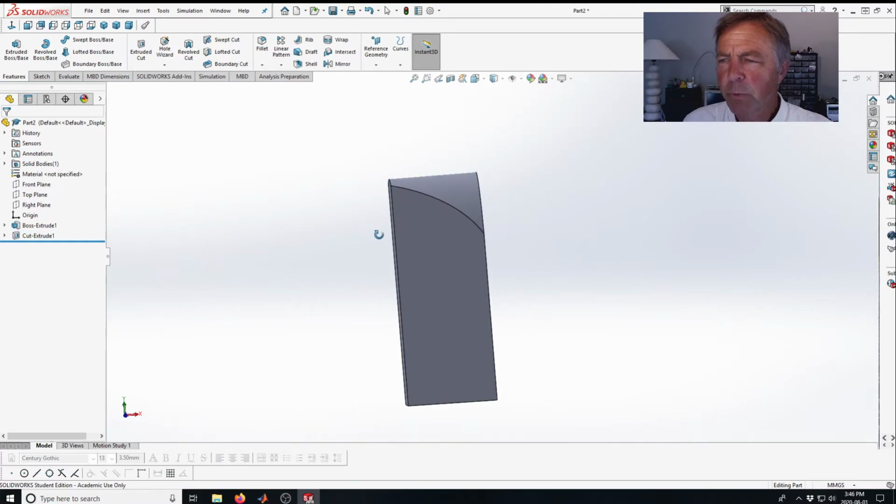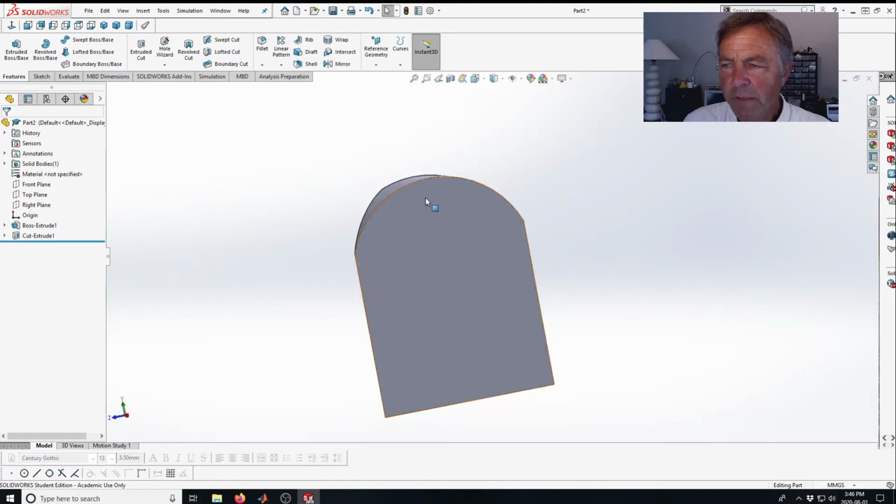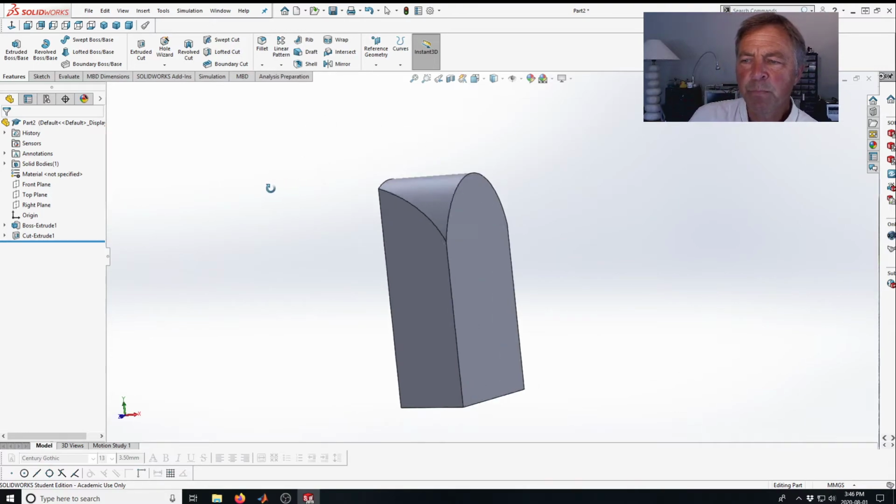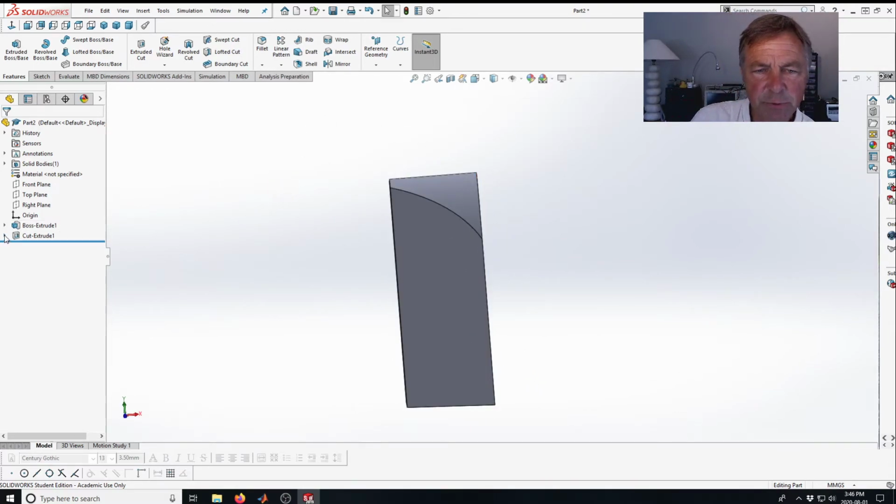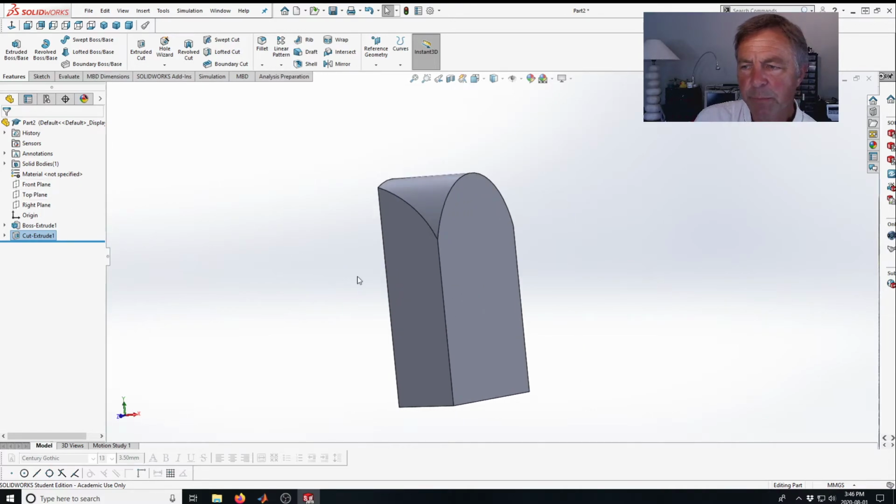But you know, what I'd really like is to have this roof line kind of sloping. I'd like to have it higher here than it is here. And there's a bunch of ways I could do that. I'm going to try messing with the way that I started that cut. Now, recall with the sketch, one of the things you can do is edit the sketch plane. You can start a sketch on any plane you like. Problem is that the only planes I have in this model are front plane, top plane, right plane, and then as I build up the model, the face planes of each of the parts.